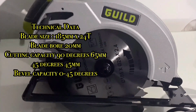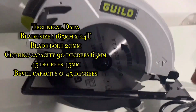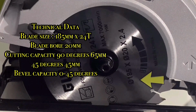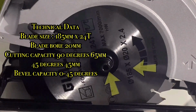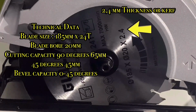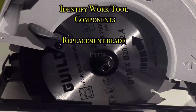If you juxtapose the technical data information side by side with the information that you've actually got on your blade, we can instantly begin to see that there is a correlation. 185 being the actual blade size or the size of the rim, 20mm being the blade bore, which is right at the center of the blade, and 2.4mm is the thickness or kerf of the blade. At a later stage, I will show you how to adjust your cutting and bevel capacity.